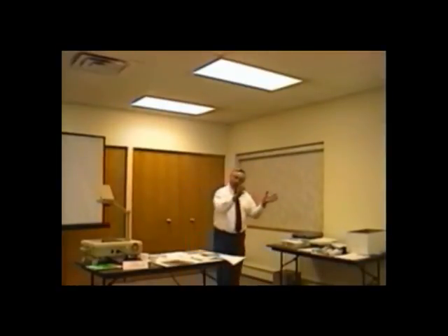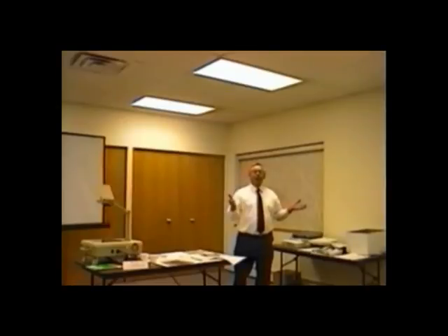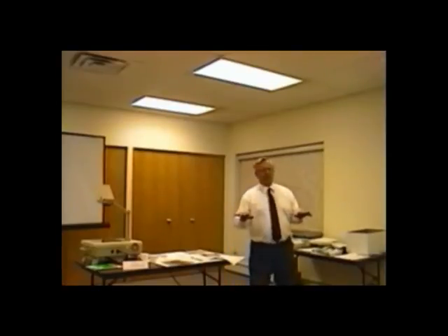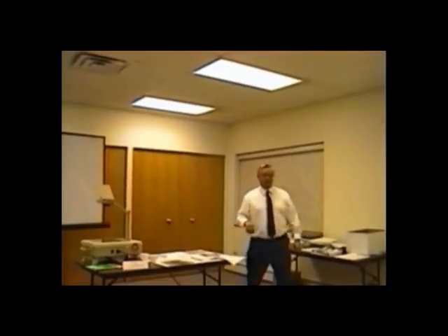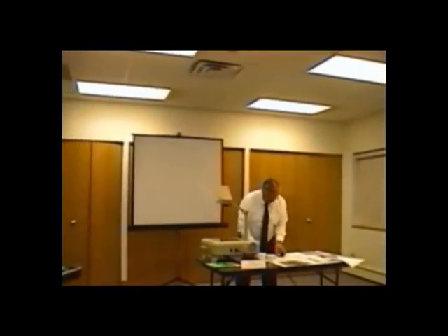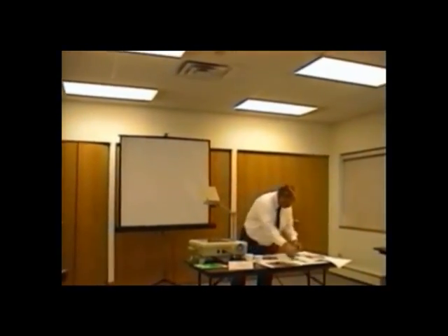But again, you can make an all-day seminar out of 410A. And the point is, you have to be careful with it. It's not a joke, and of course, I don't mean to make light of it. But you have to be careful. You need to be wearing your goggles today, even if you were very lax before with 22, because the pressures can hurt you today. You break a line, it's going to be a problem. Just keep in mind, 60% is quite a bit higher. Okay? You got any questions on that? Okay. We're winding down. I got one more thing to do with you now.